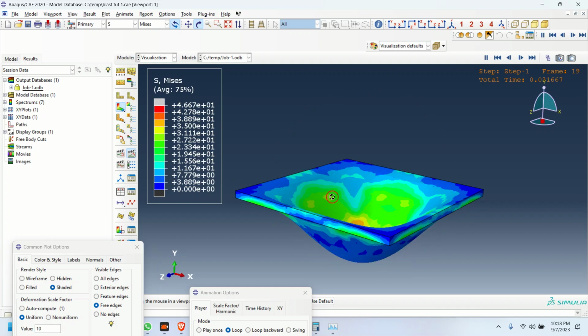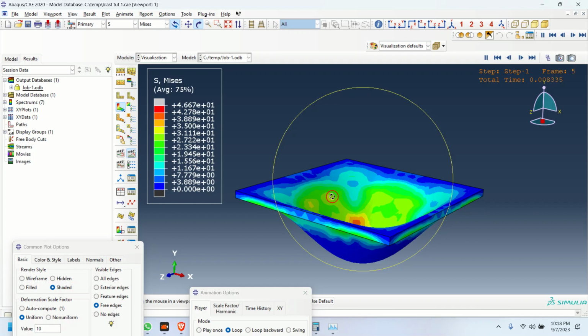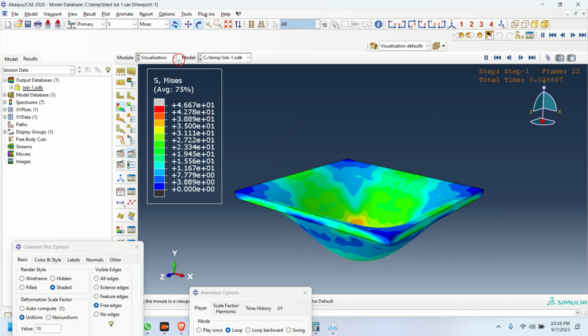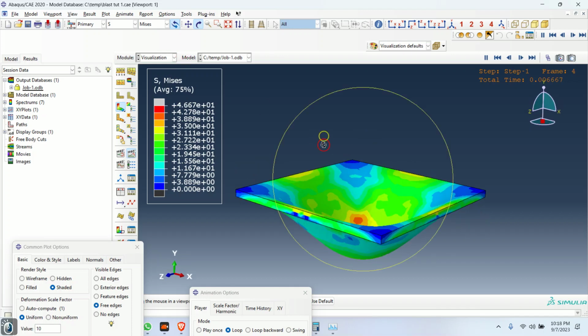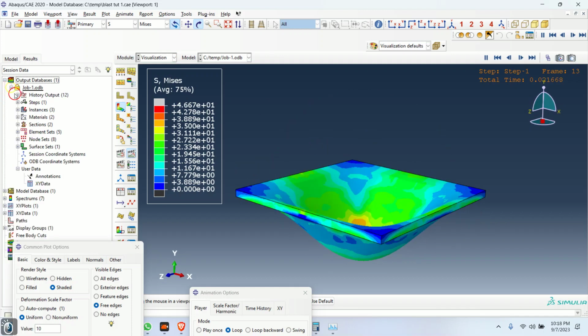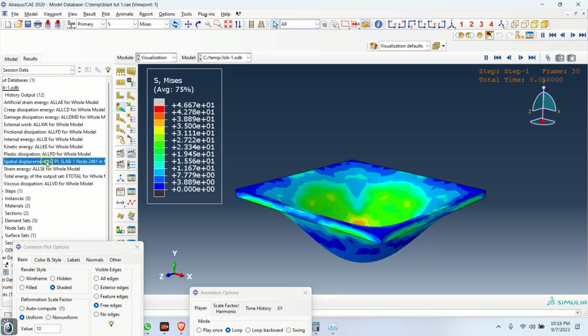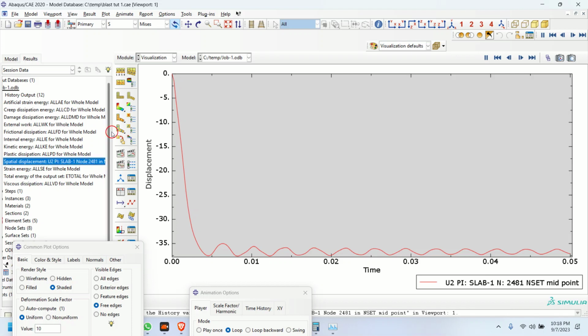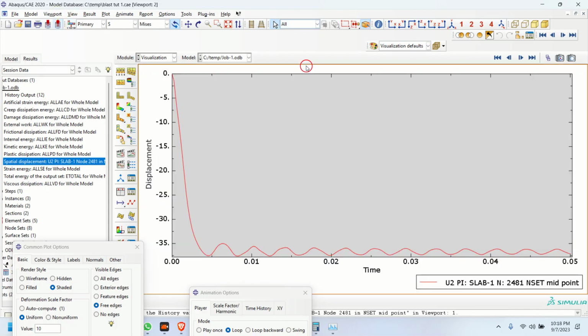Yes, usually the people do not go for all these simulations. So they find out the static pressure due to the dynamic effect of the blast and multiply it with the dynamic load factor, and then proceed with the design. Yes, that's what the people usually do. But why these values are not correct? Or what error do we generally make while doing all these things?